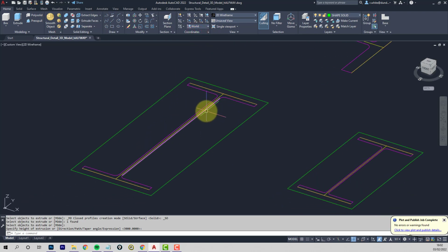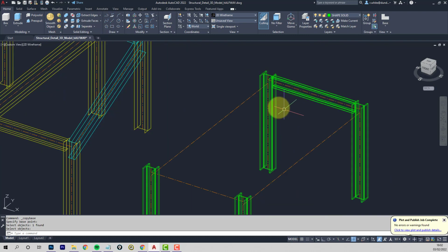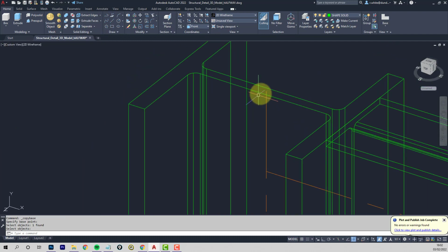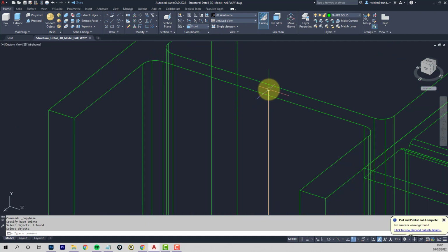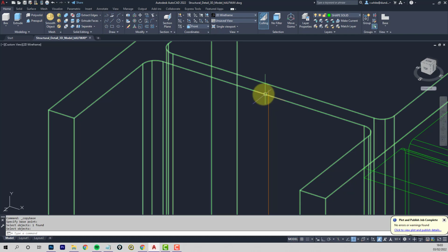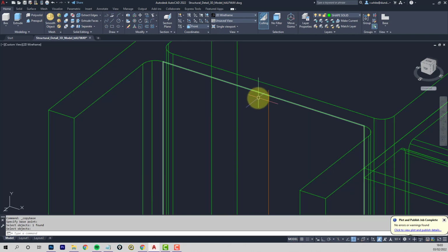Same manner, same way. Shift Control C. Use the top middle of the flange, pick the shape, enter. Okay, it's a different UCS for the placement, so we want to go to the front UCS. We want to be kind of facing the web of those columns. So front. We have to be a bit more careful with placement here. We're not placing at the top of the setting outline, it's going on the middle of the web. So Shift Control V, the midpoint of the web, explode it just once, then extrude it.